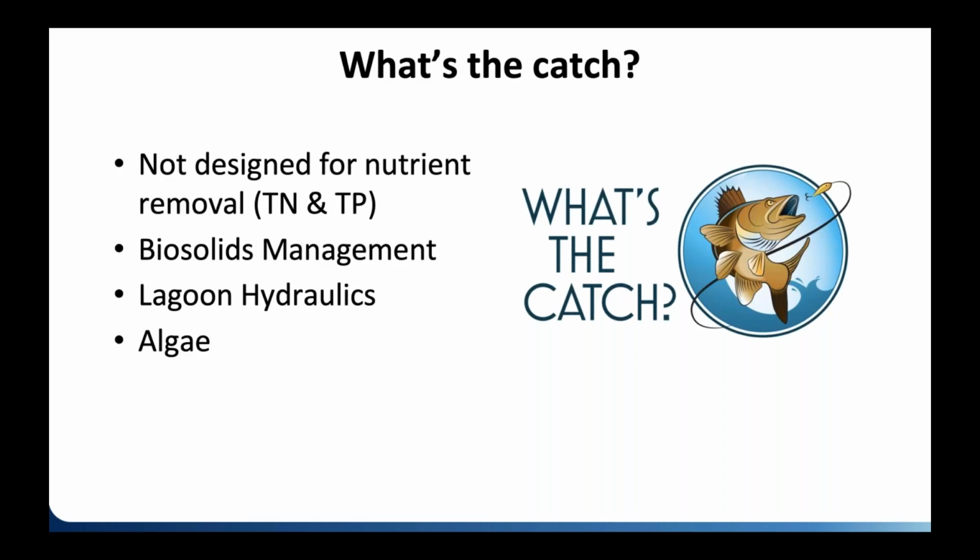And sometimes municipalities forget that, and they leave the solids in there, and they don't budget to remove the solids, and then they become a major issue later on down the road, because you can't just store solids in lagoons forever, right? Lagoon hydraulics can be an issue. That's mainly where water doesn't flow through the lagoon in the way you want it to. Sometimes it takes a shortcut, goes from one location to another location. And then finally, algae can get a little out of control, especially if you have biosolids issues.